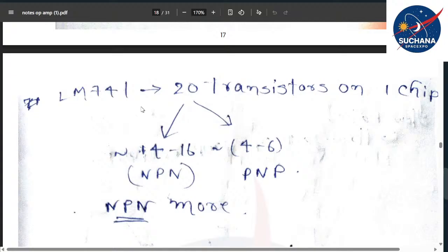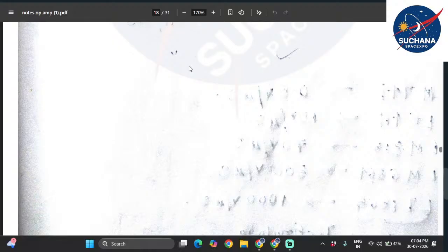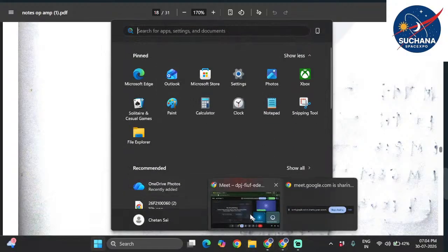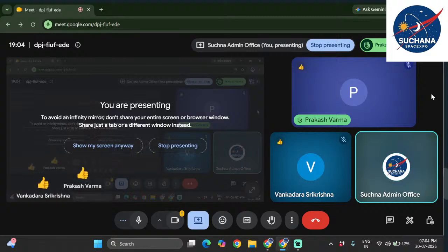So this is how an op amp can be used as an integrator. So I hope it is clear, right, everyone? Everyone, is it clear? So now I'll ask you one question. So we already know that V out of t, that means the output voltage, is equal to minus 1 by R into CF into the integration of V in of t into dt.